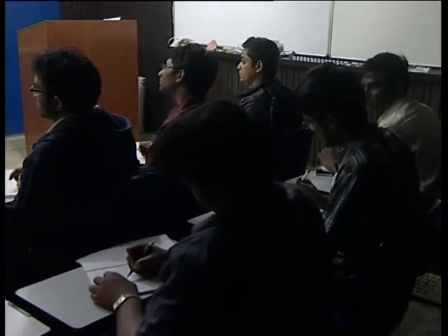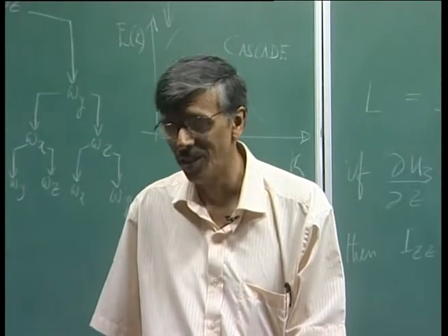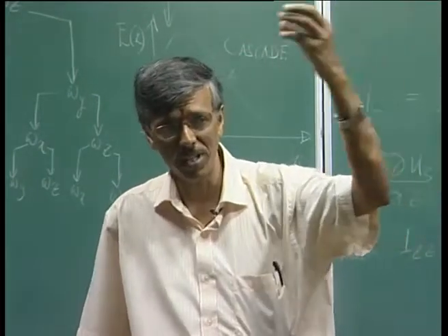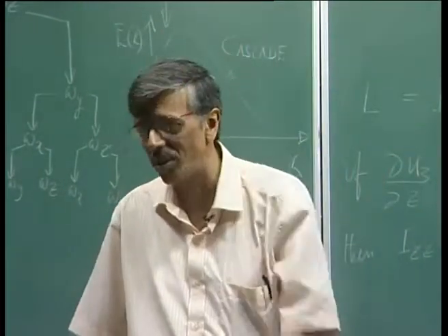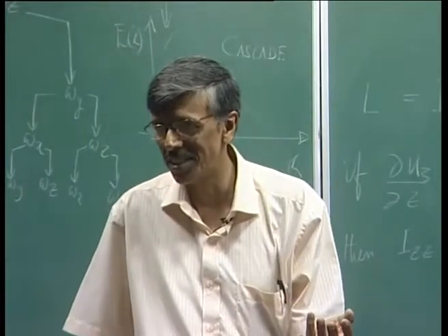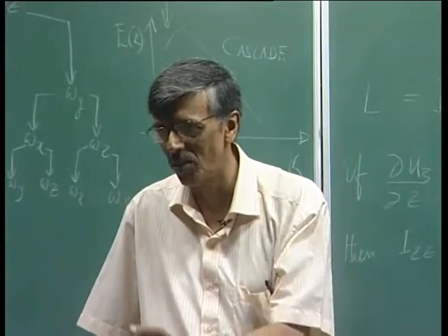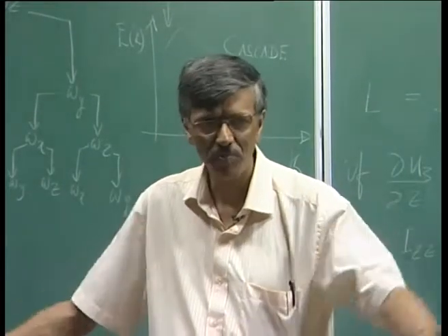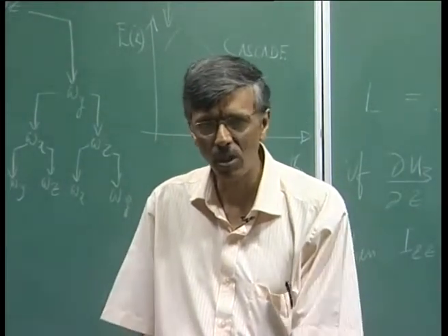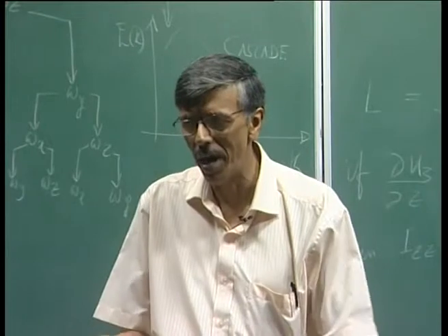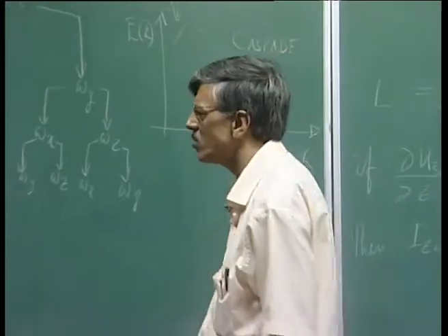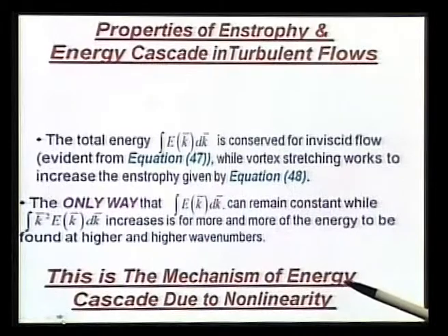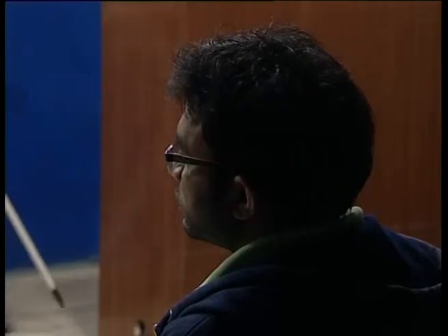Then we have also seen bypass transition effects. What did we see? That if a single vortex is simply moving at a constant speed, there is no trace of any unsteadiness. But what happens down below in the boundary layer? We get vortices erupting all over the no slip boundary, and that is a very high wide band phenomenon. But please do understand that for 3D flows at least, vortex stretching helps you explain how energy is transported from low k to high k.